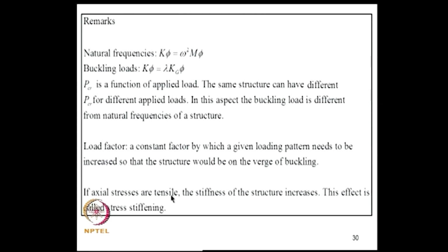If axial stresses are tensile, the stiffness of the structure increases. This effect is called stress stiffening. So, in a more general problem, this will automatically get accounted for based on the sign of the axial thrust. So, that automatically will be included in the analysis.